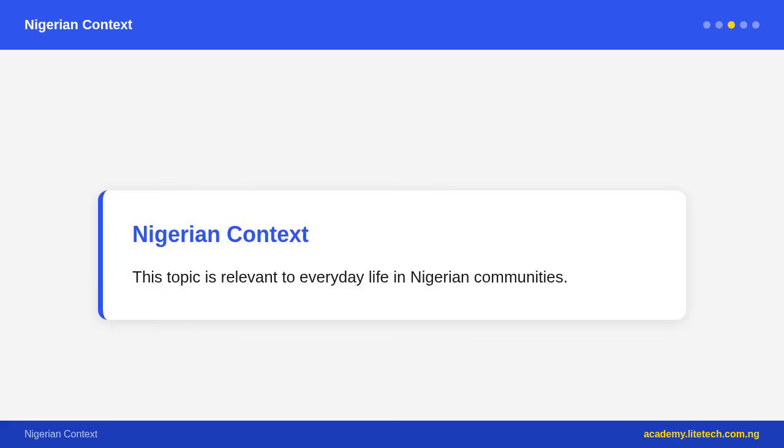Proximity effect, a phenomenon of directional microphones including cardioid, causes a boost in bass frequencies when the microphone is placed very close to the source. Experienced vocalists use this deliberately to add warmth to their voice. Be aware that less experienced vocalists can accidentally create a booming, unbalanced bass sound through excessive proximity.